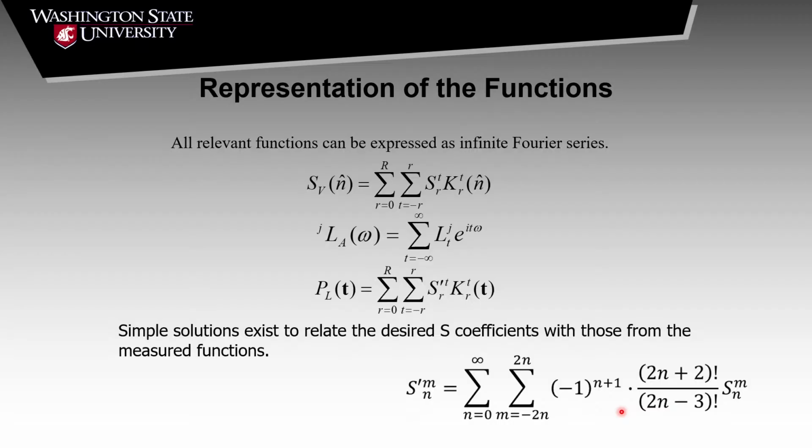Now the mathematics to get to this solution is very, very, very involved. You go to Hilliard's paper and read that about 100 times, and then you'll understand it. That's how long it took me, about 100 reads, right? Then all of a sudden I just said, wow, it's a very, very simple solution. So I take what I measure, I grab those coefficients, I do some simple algebra, and then I know the coefficients for surface area per unit volume, where I've never actually measured the grain boundary normal. I haven't ever measured a grain boundary normal. I've just measured how many times I hit that boundary with a given scan line. Okay?